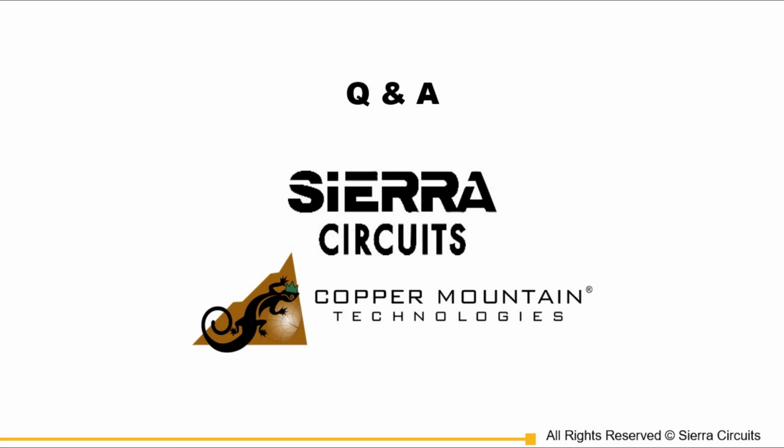So you could look at what's going on between 1 and 3 nanoseconds very nicely. Whereas if you did that with an inverse Fourier transform, you did a bunch of points, you got the resolution, whatever you got, but if you zoomed in on it, the result would be chunky. You have a lot of little steps in it. The inverse chirp Z transform allows you to pick the range that you want and have that output from the transform with all the number of points that you've already chosen.